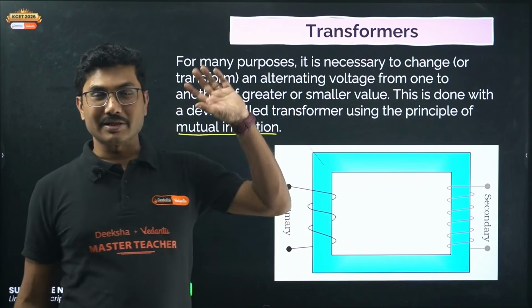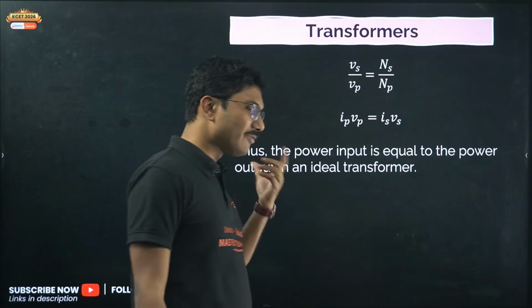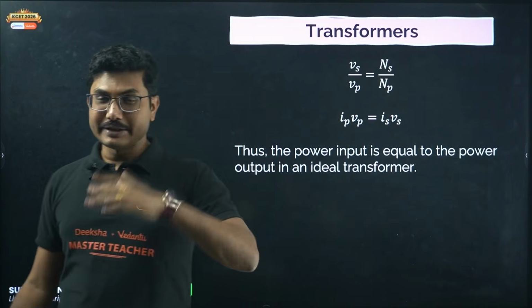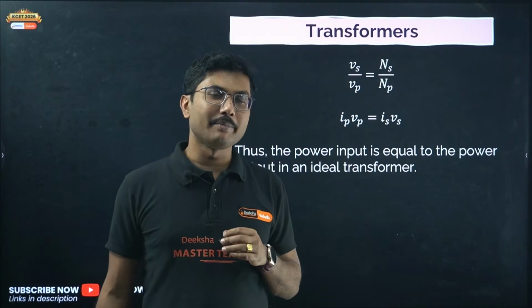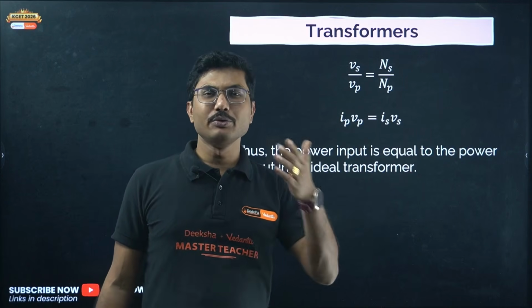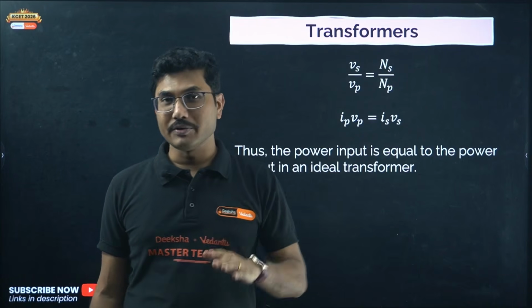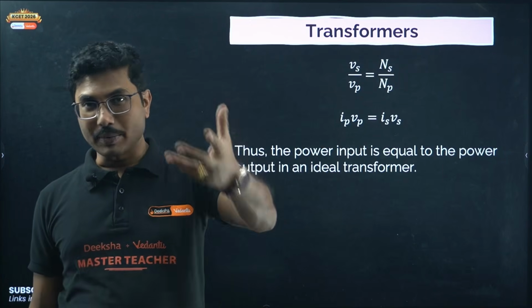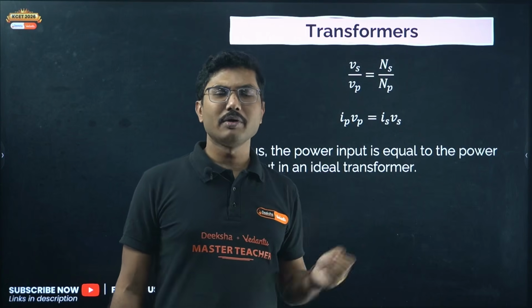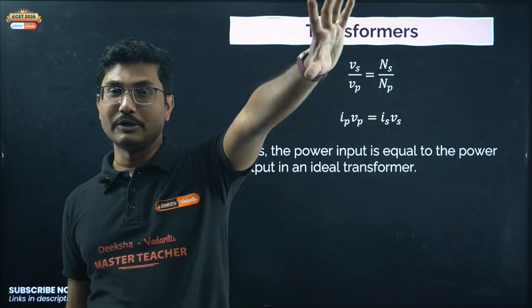So when the current is being transferred from the power station, it is transferred at a high voltage. Okay, and when that high voltage is being transferred, it consumes a very less amount of power. Now when it reaches your home, if the same high voltage is supplied back to you, all of your appliances will fry off. So that's why they use some stages to lower that voltage. First it is lowered from that high kilovolt to 440 volt. Okay, that 440 volt is supplied to industry directly, because all industrial equipment is required to operate at 440 volt, and then that 440 volt is reduced again near the pole which is located near your house.